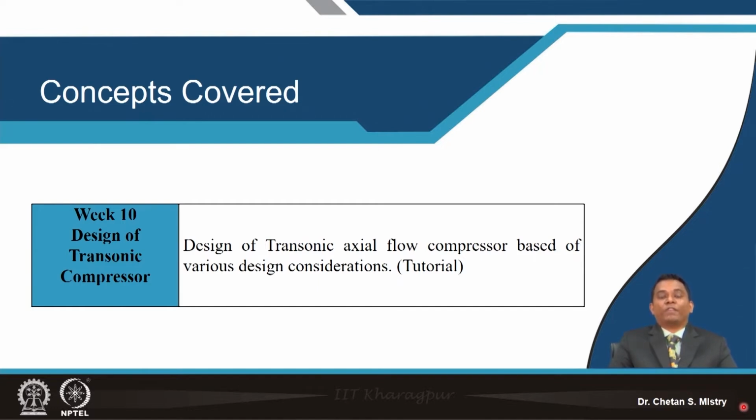That includes the fundamental method. We have also discussed design of fan using control vortex concept. We have discussed different track configurations in the sense of constant tip diameter, constant hub diameter, constant mean diameter, or we can say by assuming various radius ratios. We have also discussed how exactly we will be configuring our design, maybe which will be fulfilling the requirement of radial equilibrium, or which may be violating radial equilibrium.